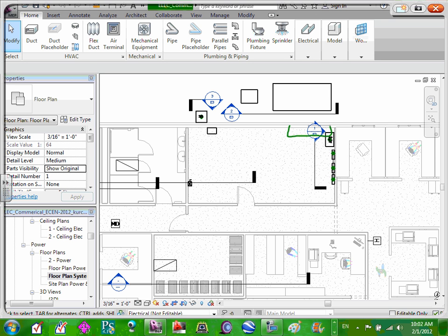So it says here, and this is another thing that you would coordinate with your mechanical engineer, that you have 2 tamper switches and 1 flow switch. I'll start with the flow switch. There's probably either 1 or 2 zones for this building. Zones being, there's sprinkler piping going out here and distributing to this area, and maybe that's 1 zone, and then there's a zone here going out to this area of the building.